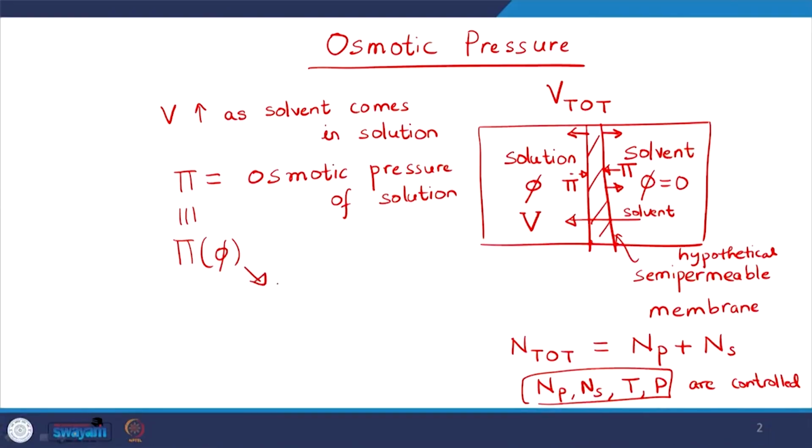So, you have a large concentration gradient, so to speak, to begin with. When phi decreases as volume increases, that concentration gradient becomes smaller. That should result in a lower osmotic pressure, or a lower requirement of pressure to keep the membrane at a fixed volume, right. So, this must be a function of the volume fraction, and this in some sense is what characterizes the mixing behavior for this particular problem.